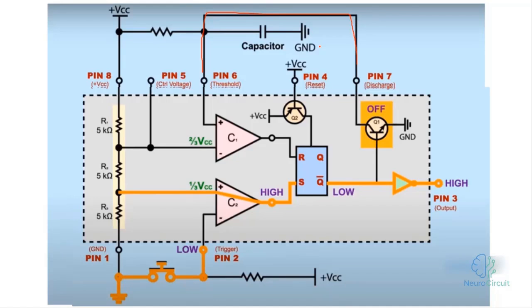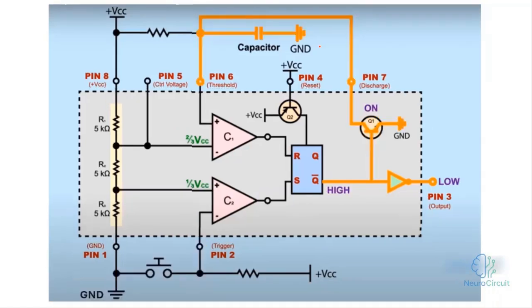Now, we said that in this setup, where I connected pin 7 to pin 6 and then connected it to ground and VCC through a resistor and capacitor, what does this do for us? When you look at it like this here, when the output of the 555 is in the low state, you can see, just like in the previous 2 diagrams, obviously my flip-flop's not Q is in the high state, and this causes the transistor to turn on.